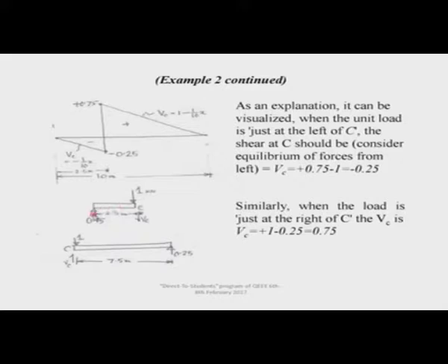So, here you have a shear force upward 0.75, downward 1, so you have downward 0.25. According to your sign convention, when you look towards the left of the section, you have already agreed that it will be positive. So, it says I have a downward force of 0.25. Definitely, according to your sign convention in the influence line diagram, you must plot that shear as negative. So, this is plotted as 0.25, that is why it is negative. You can see the shear force diagram and the influence line for shear force at this location, and now you can digest that.